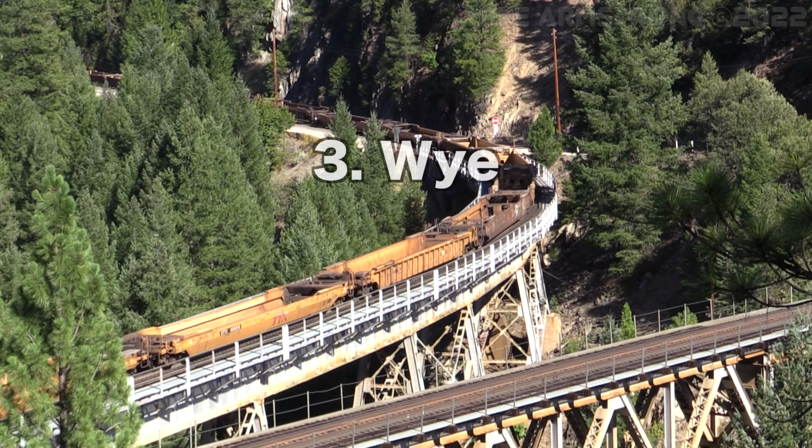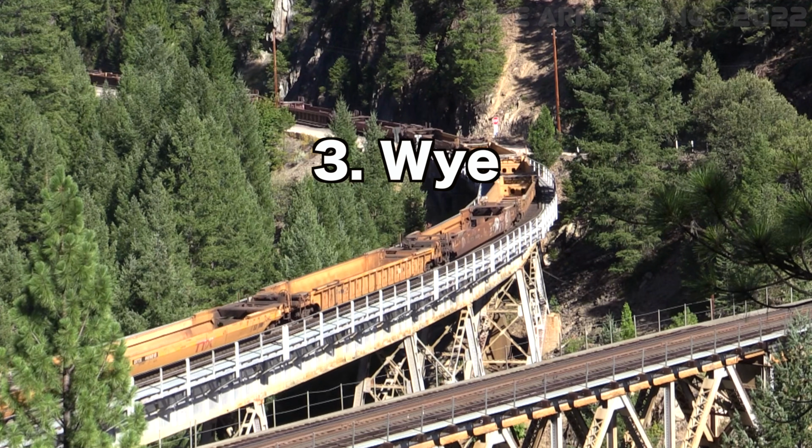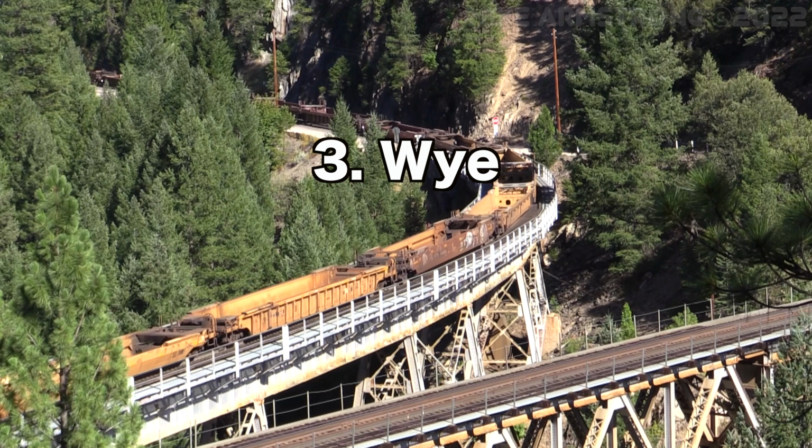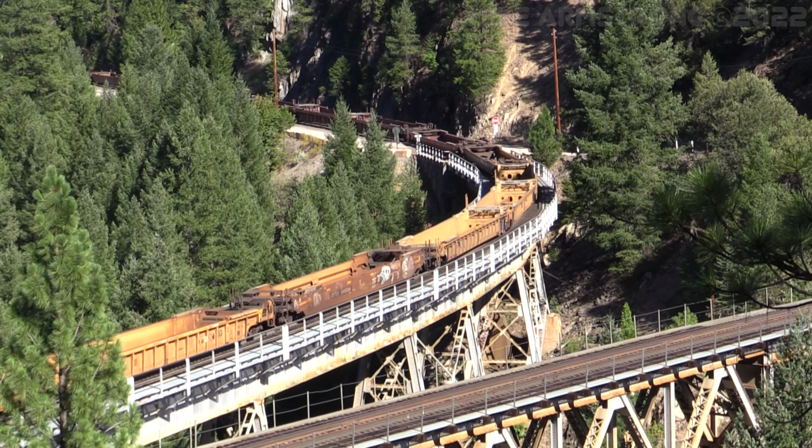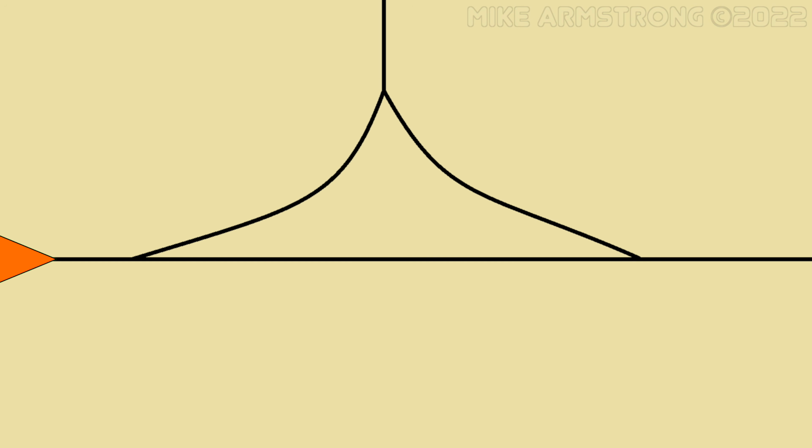The third option for turning a train around is a triangular-shaped piece of track that is known as a Y. A Y is basically a three-point turn for trains or individual locomotives. It features two pieces of track that come off a main line from opposite directions, known as the Y's legs, that connect together at a switch. A tail track extends past the end of the junction of the two legs of the Y to allow rail equipment to sufficiently clear the switch.